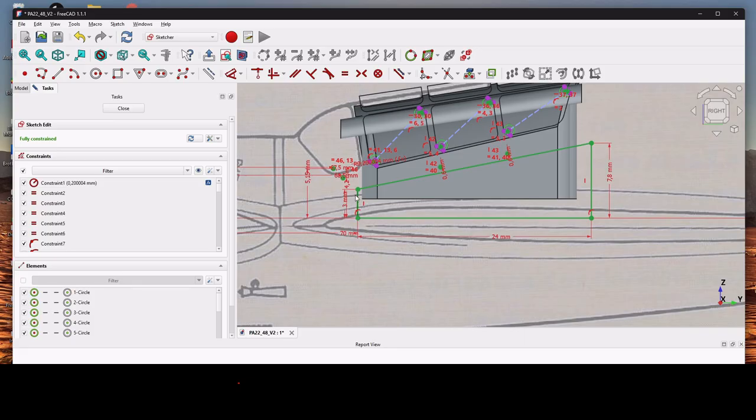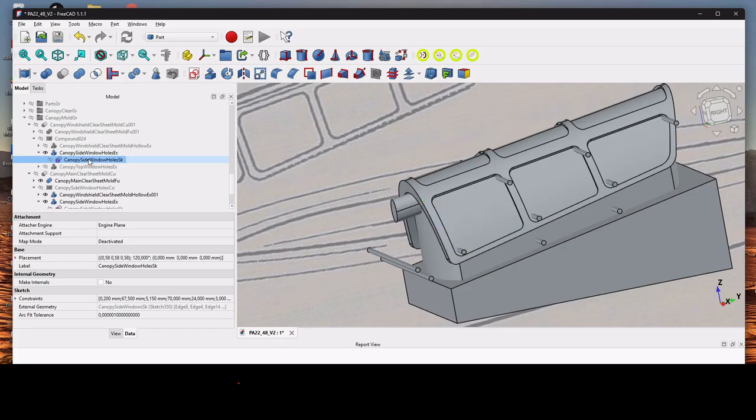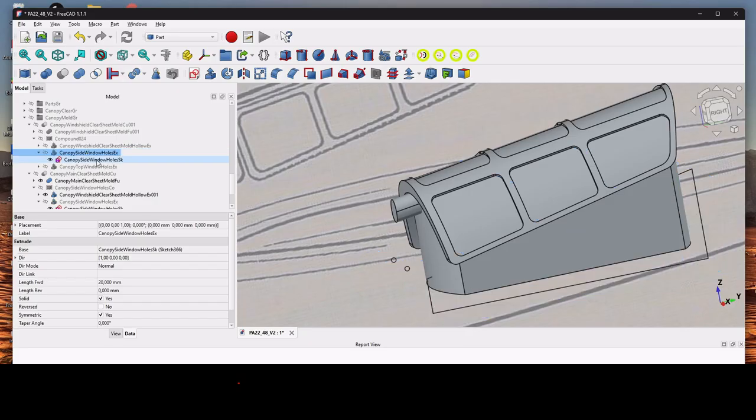But also I've used that side holes in order to make sure that I remove some matter, because I do not want that mold to be too high with respect to the plastic sheet that I will use to thermoform. So I'm cutting the basis in order to make sure that this is close to what I'm using when I will do the thermoforming. And at the end of the day, these are the holes that I'm using.